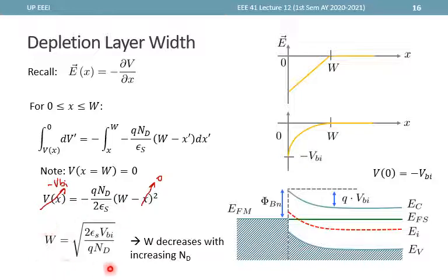And from this equation, this one is actually of the same form as what we have with our p-n junction. It is specifically equal to the case where we have a p+n junction. So this time we can make an analogy that the metal acts like the p+ and the n side acts as the n side.